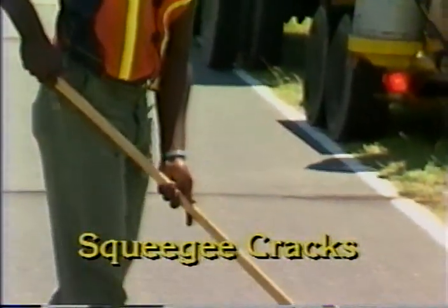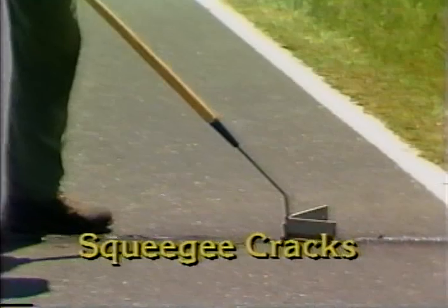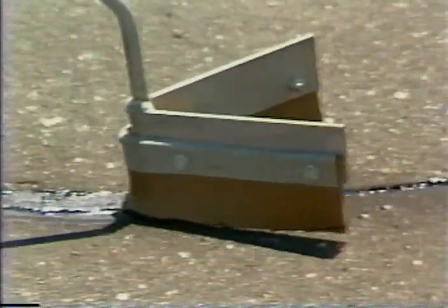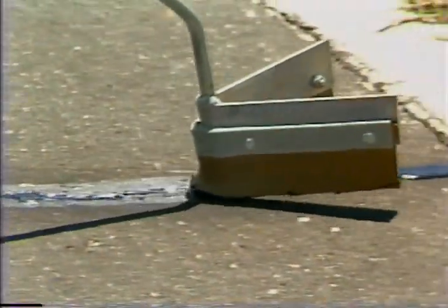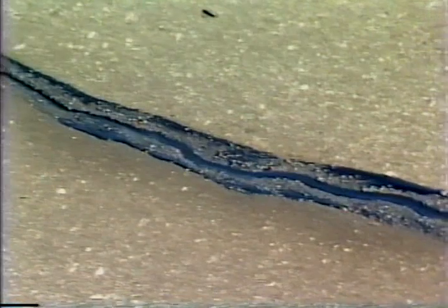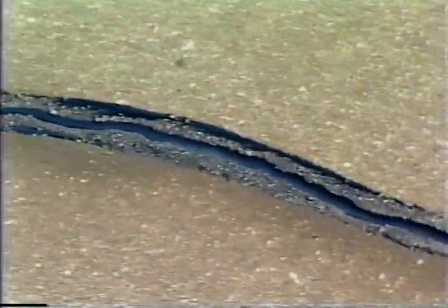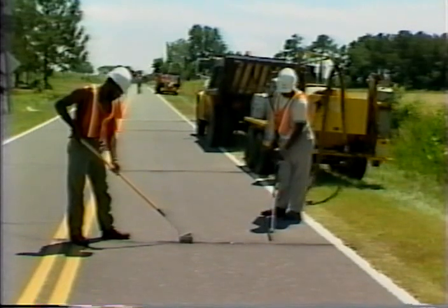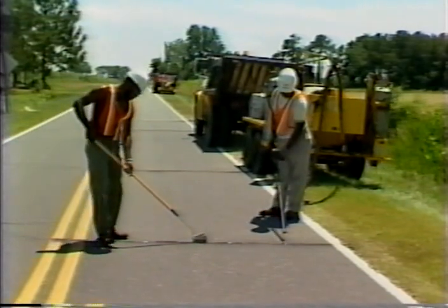The fourth step is to squeegee the just sealed cracks. The squeegee operation levels and smooths out any excess sealant. It results in a thin film of sealant across the pavement that aids in sealing the crack. This operation follows immediately behind the applicator, usually within 5 feet.